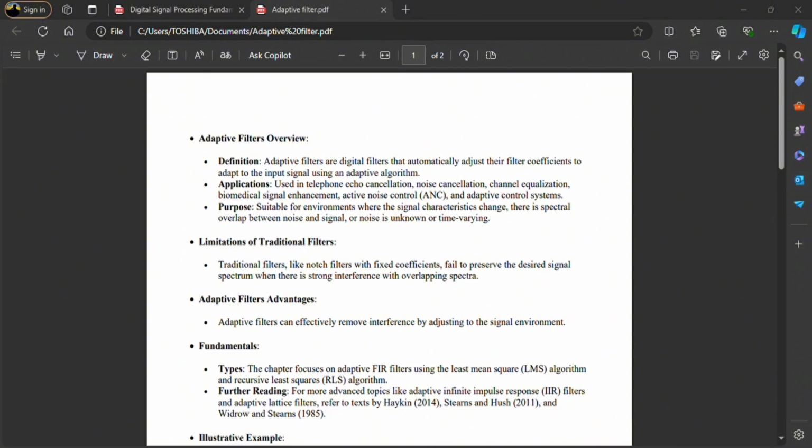Adaptive filters are required for some applications because some parameters of the desired processing operations, for instance, the location of reflective surfaces in a reverberant space, are not known in advance or are changing. The closed-loop adaptive filter uses feedback in the form of an error signal to define its transfer function.